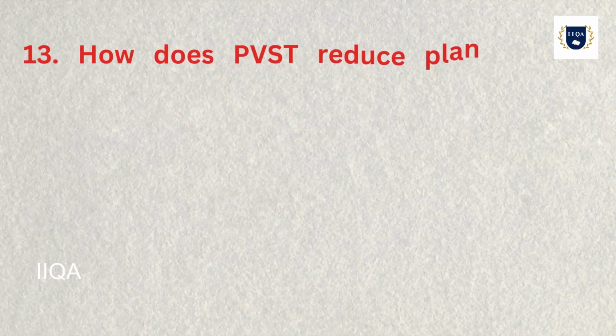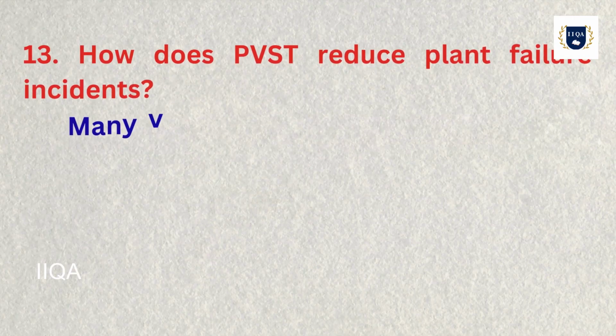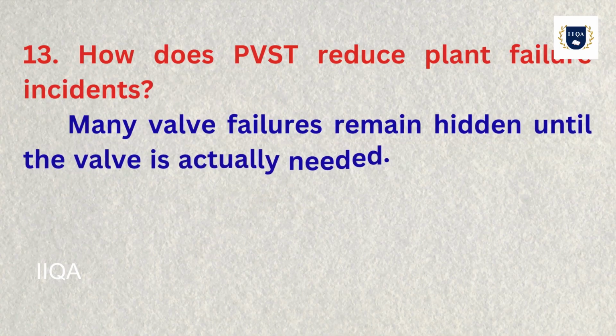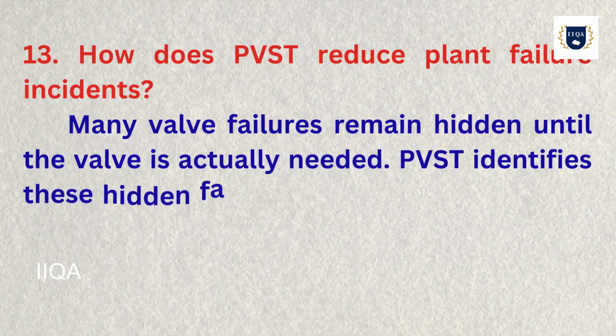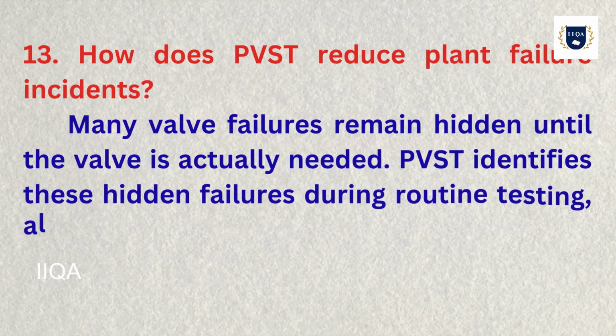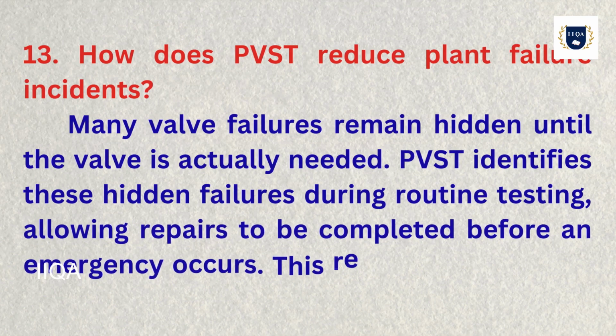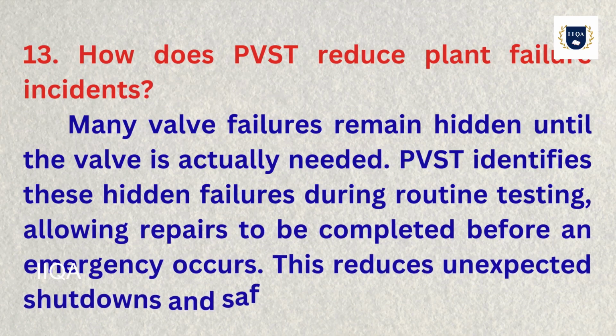13. How does PVST reduce plant failure incidents? Many valve failures remain hidden until the valve is actually needed. PVST identifies these hidden failures during routine testing, allowing repairs to be completed before an emergency occurs. This reduces unexpected shutdowns and safety incidents.